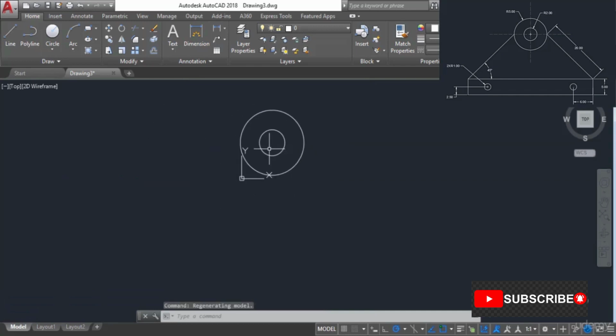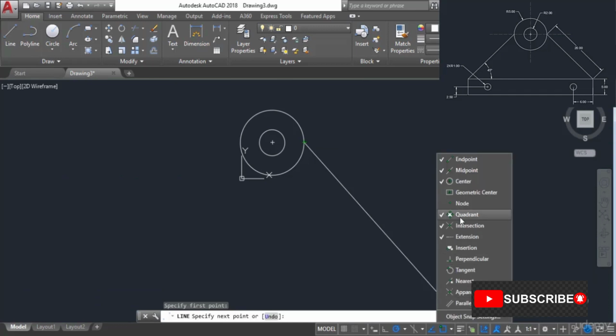Now let's start with the line tool. So I'll click on line and now click at this quadrant, and if the quadrant is not visible, then you can click on this object snap option, and right beside that there is this small arrow. So just click on it and turn on this quadrant. Although this is a tool which we'll learn later on, a little bit of knowledge of this tool is very helpful in making these kinds of drawings. So you can turn on quadrant to see that point.